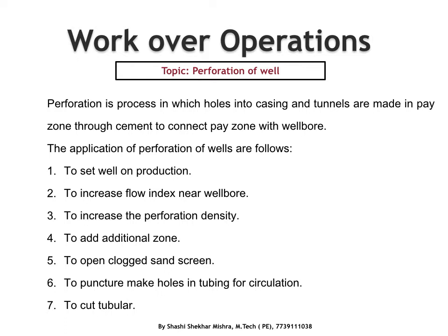Then suppose a completion is in open hole with a sand screen to control the sand, and with time the sand screen has clogged and we are not able to clean it and it is hampering the production. In that case also we make holes in the sand screen, sacrificing the sand screen itself, to have the production.